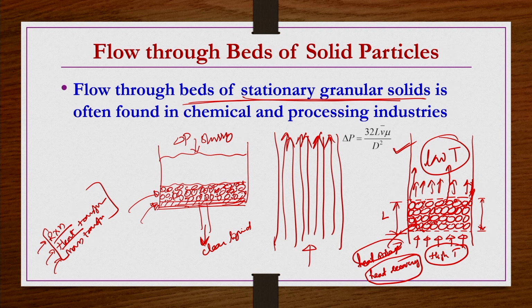So, whatever study or analysis that we are going to do here is going to be there in all of these things, right. Whatever reaction, heat and mass transfer are expected to be carried out in this packed bed will not be possible unless there is a momentum transfer. So, how much pressure drop is required for a given flow rate of liquid to flow through a packed bed having certain characteristics like voidage, packing particle size, dP, etc.? So, this dP we are going to find out.